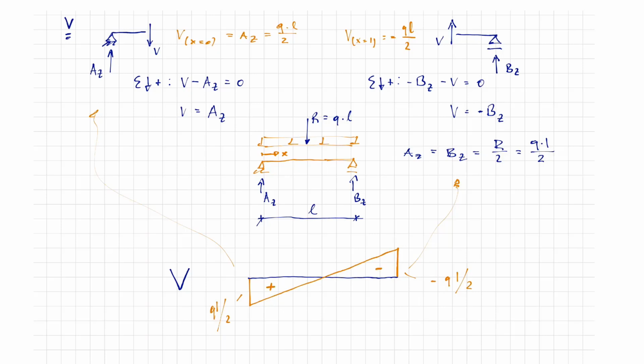In the case of constant distributed loads, the shear force distribution is linear. If concentrated loads are added, the distribution also shows jumps. You obtain the exact value of the jump by the section at the location of the concentrated load. We will determine the moment and axial force distribution in the next tutorial.